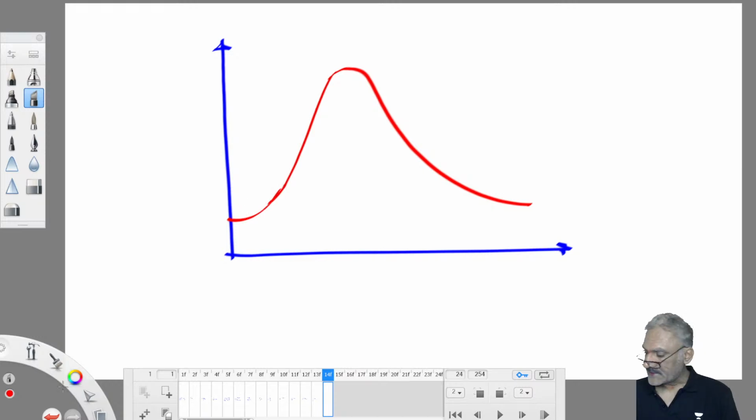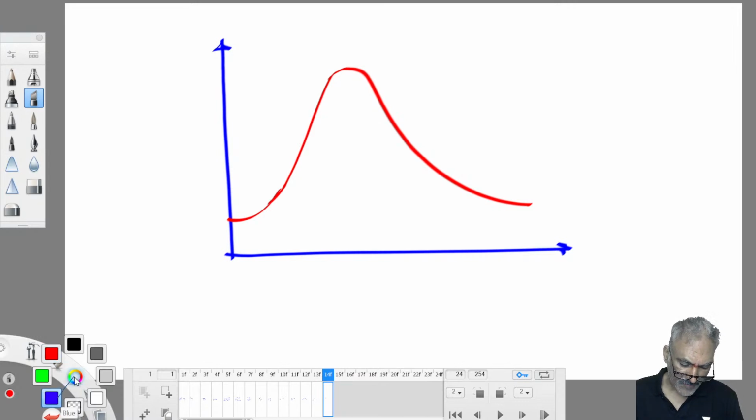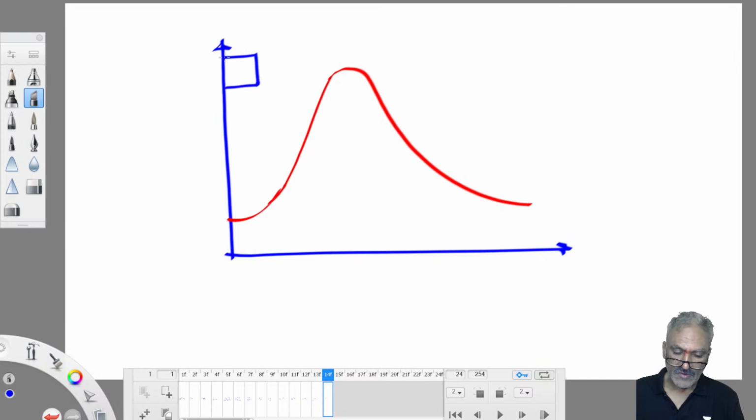So, the hydrograph which we get for a given storm is true for that storm only. For some other storm you can't apply. That means the storm hydrographs or flood hydrographs vary. For every storm you have to measure. Therefore, that storm information also we mention in the hydrograph. We are talking about which storm.